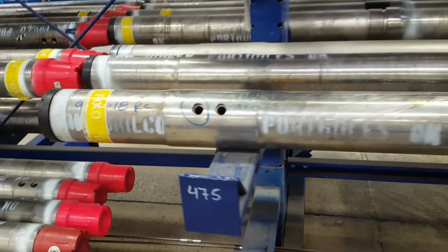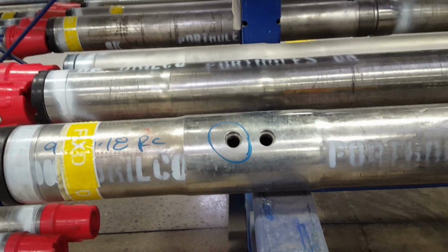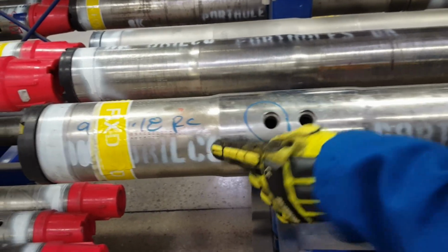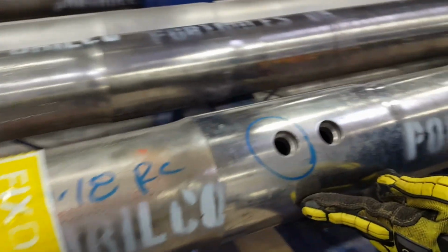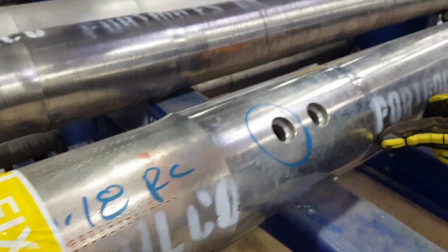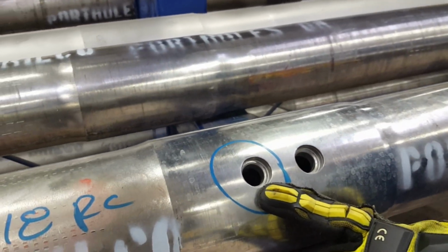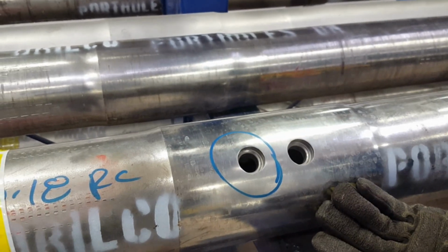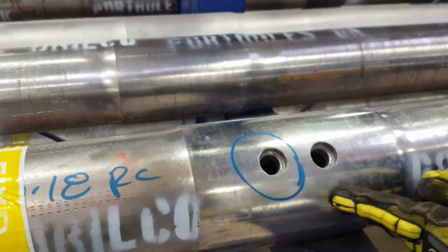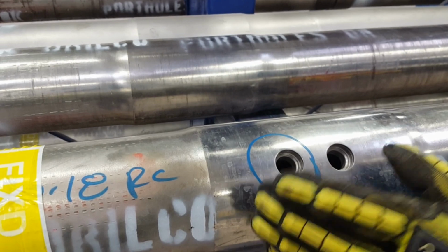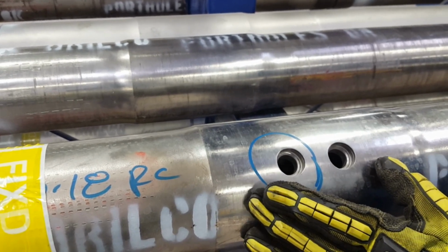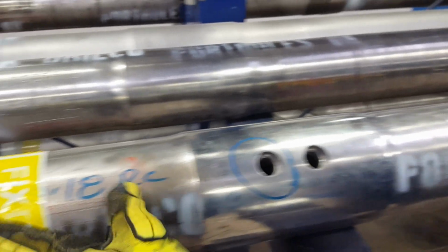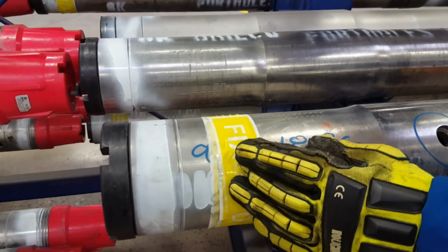So this is a 525 power drive collar, which instead of being 475 has an upset. You can see how it gets slightly bigger here on the OD. And it uses larger bolts that go inside. So this is, if you've ever seen the 45-degree cracking that happens on the collars, this upset is designed to make this part of the connection stronger, this part of the collar stronger. It doesn't have the real-time float bolts at all on these 525 collars.